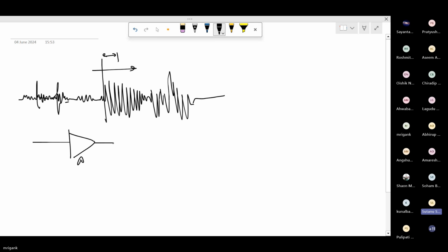Because these signals may be of low frequency, and in amplifiers we will have 1/f noise in the low frequency range. So we need to use proper stabilization, maybe chopper stabilization. I have not taught you that; I think it is there in one of my recorded lectures. Have you gone through that lecture? Yes, sir. So right now I have not covered it. So for the time being, I will not consider chopper stabilization. It was a simple concept only, but for the time being, assume that we are not looking at that.